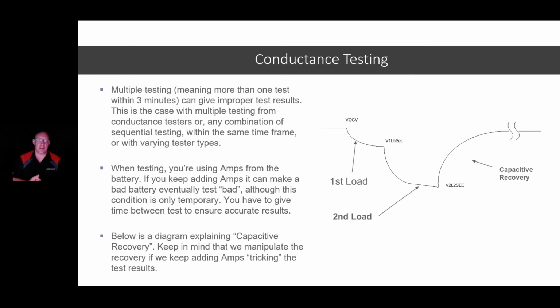So it's important to not discount what they say, but certainly in today's day and age with the electronics we have, this conductance testing is very, very finite. There's a very fine accuracy to it, and you can skew that test by making the wrong mistake in the testing process, okay? So be careful with the testing process, be accurate with your testing process and the conductance testing.